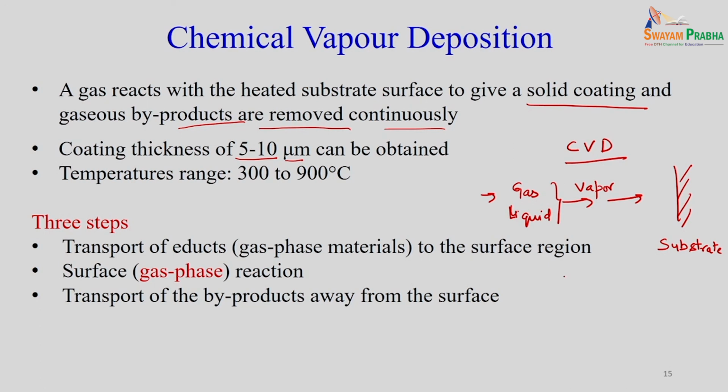So, either you go for PVD or you go for CVD. With time, this will be the coating thickness. It will keep on increasing like this. Again, this depends on what the target material is and what the rate of deposition is. Rather than reaching a plateau, it can also be a straight line, meaning with an increase in deposition time, the thickness is increasing.